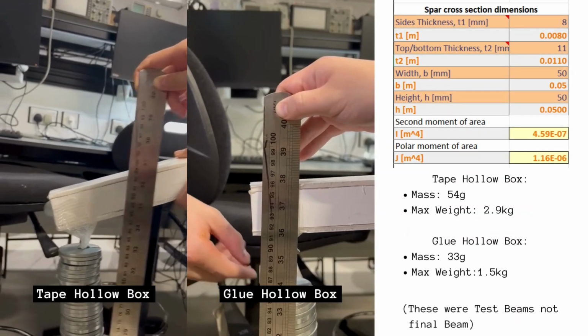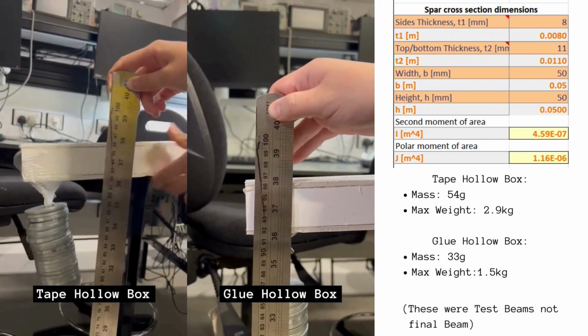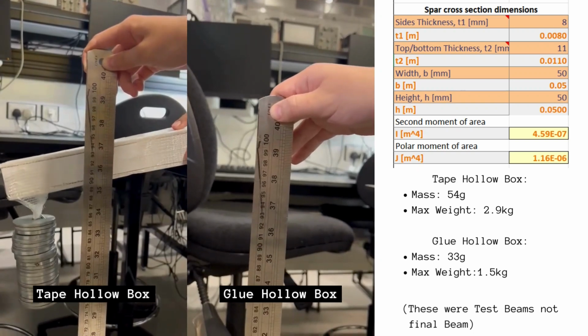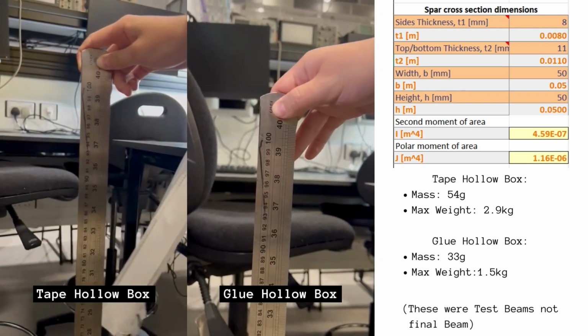The first test we did was between 2 beams, one made using hot glue and one using tape. From the results we can see that the beam made using tape held almost double the weight of the beam made using glue, but the trade-off was that the mass of the beam had almost doubled.